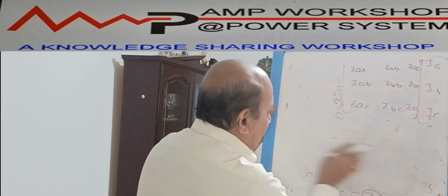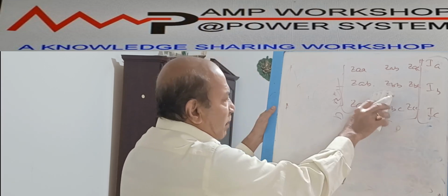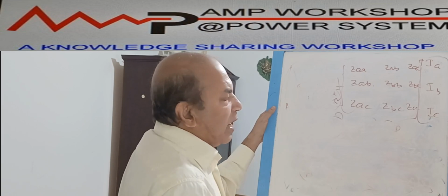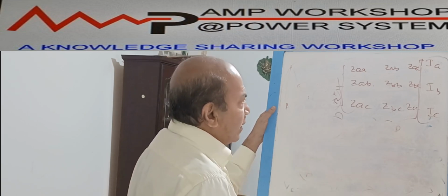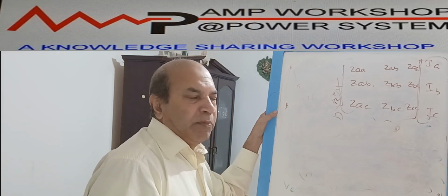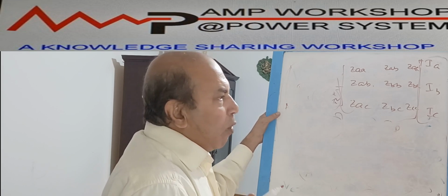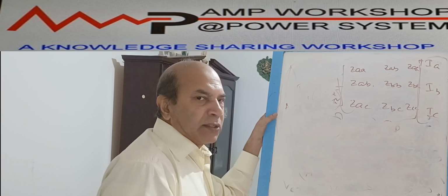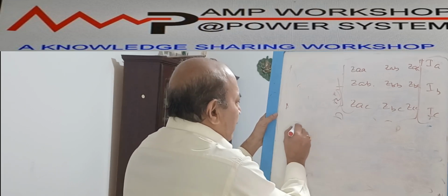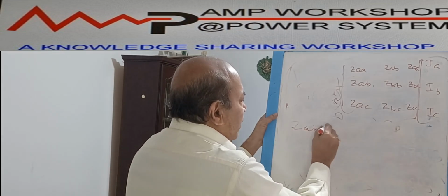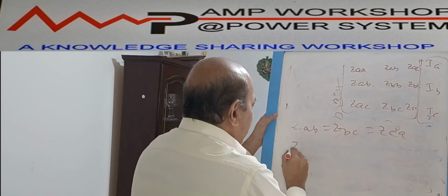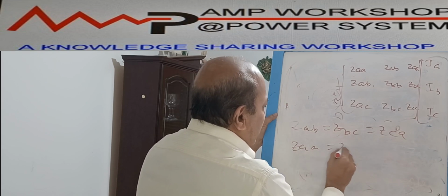Then if you do this multiplication, first this Z3 matrix will be multiplied by A matrix, and then that again multiplied by A inverse. And second assumption, these three-phase lines are balanced symmetrical three-phase lines. Balanced line means all the lines, the mutual inductance or mutual impedance between the phases are equal. That means in case of balanced system, ZAB equal to ZBC equal to ZCA and ZAA equal to ZBB equal